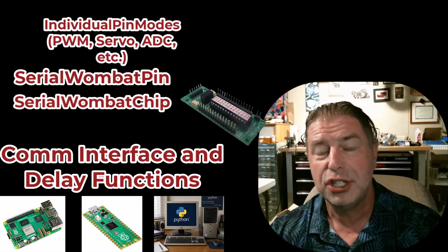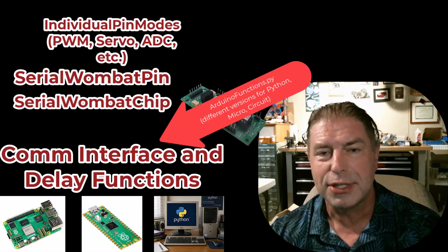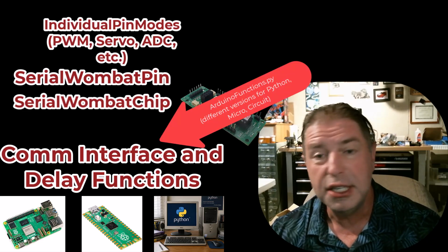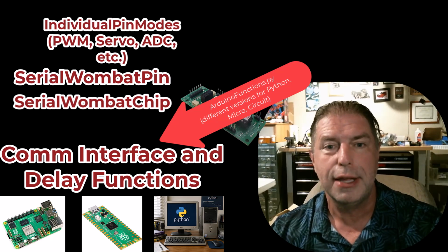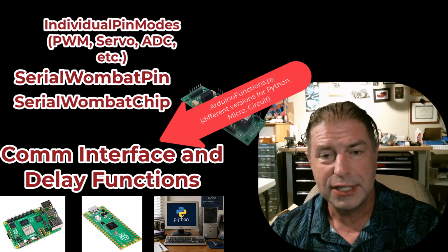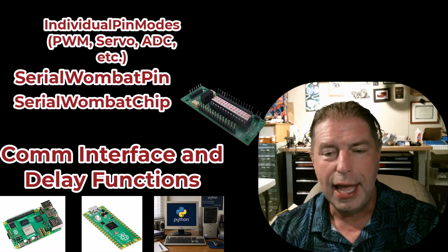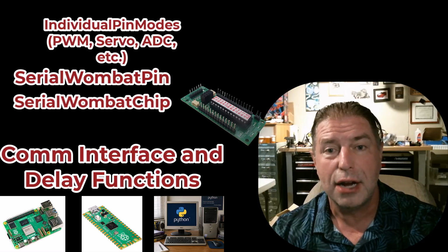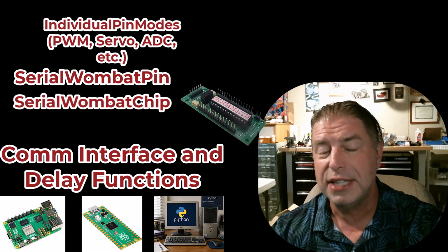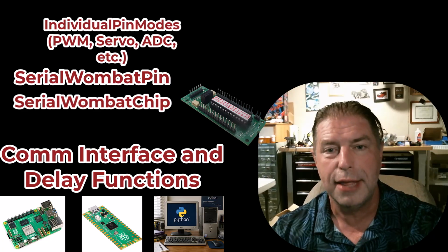Additionally, we need some generic functions that delay a certain number of milliseconds or microseconds, and some other things, like yielding the processor. For each platform, CPython, MicroPython, and CircuitPython, there's an Arduino functions.py file that you'll pull in. Those implement the delay functions the same as they are on Arduino, so it makes for really easy code porting and comparison between the Arduino code and the Python code.